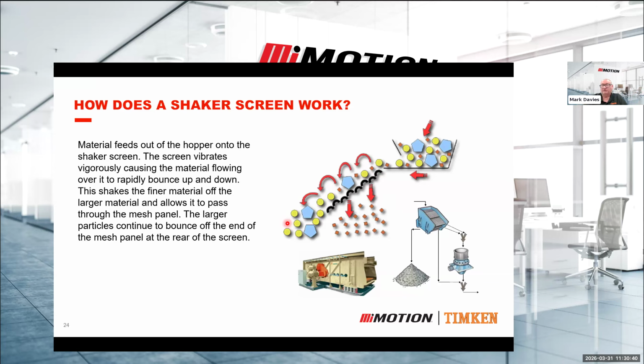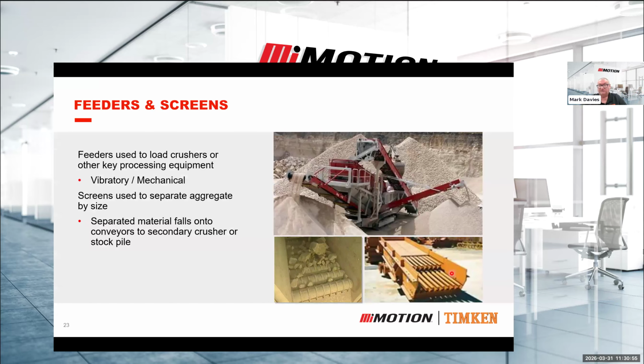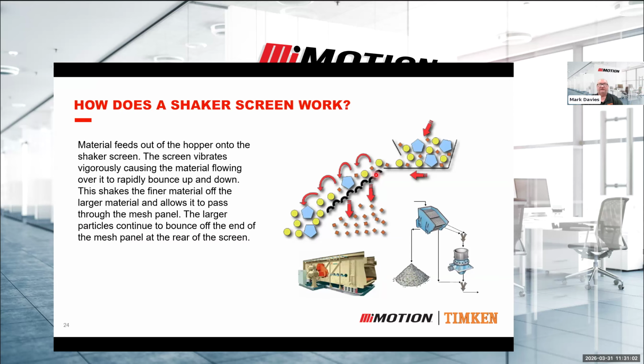If it's a dewatering screen, it's more often than not horizontal like this picture here, and it's designed so it shakes off the maximum amount of water before it gets to the end of the screen. But commonly, you'll see most of them inclined, and if I go back one screen, you can see how that's inclined, again, to feed the product down the screen and feed it off the end.